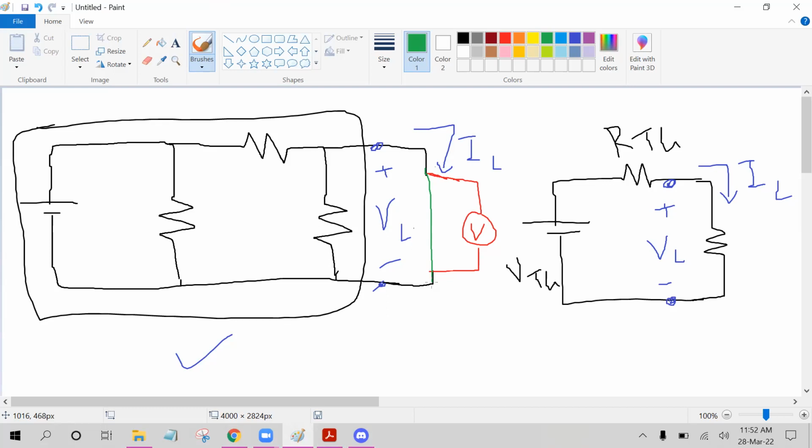So it is necessary to understand how to connect an ammeter or how to take reading from an ammeter. So just for this single task, today we are going to use an ammeter. First tell me, how do we connect an ammeter in a circuit? In series, sir. In series, right? Okay. So if we want to measure this current, we need to connect an ammeter in this series path, right here, right?